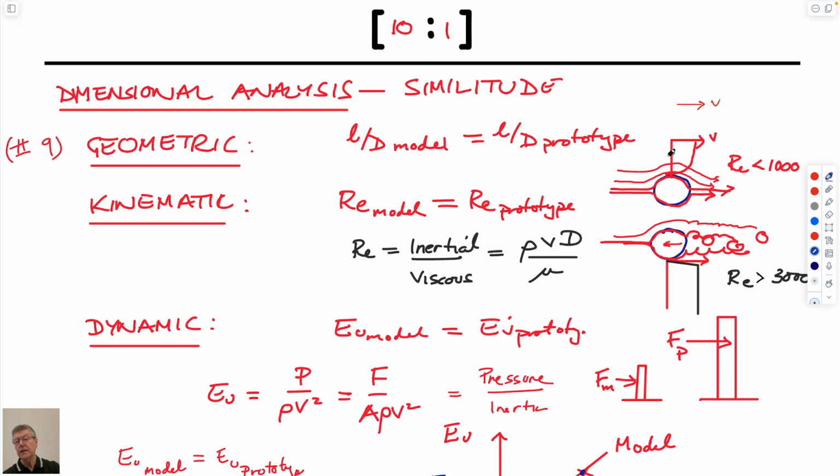If you looked at the velocities around that sphere or cylinder as you go out, we have this no-flow boundary condition where the air, water, is stuck to the boundary of this. So the velocity here is 0, but as you go further and further away from it, you'll get closer and closer to the far field velocity, which is the same as the upstream velocity.